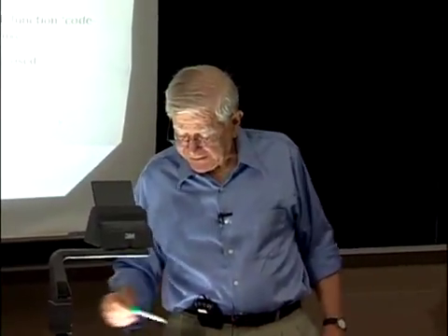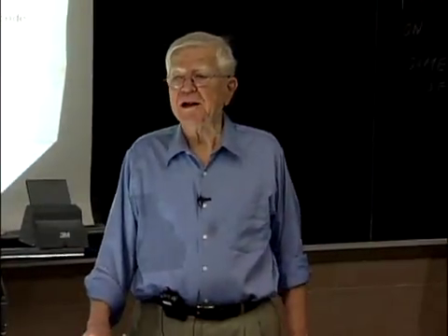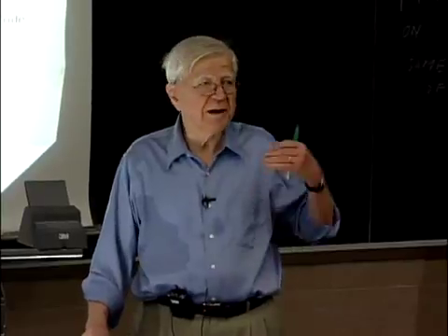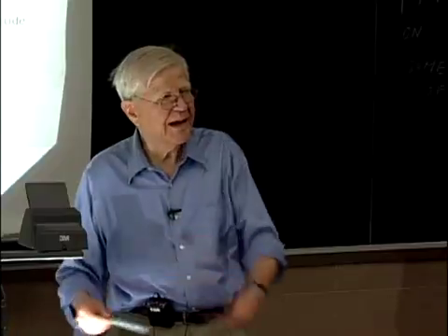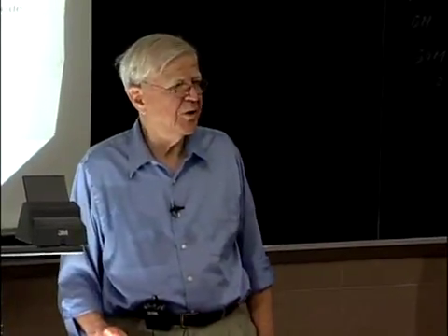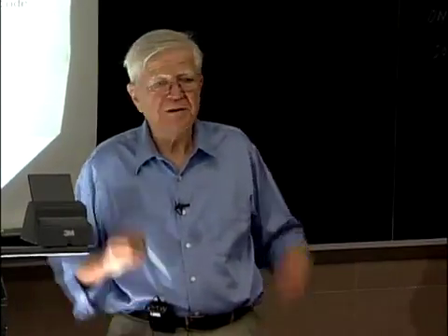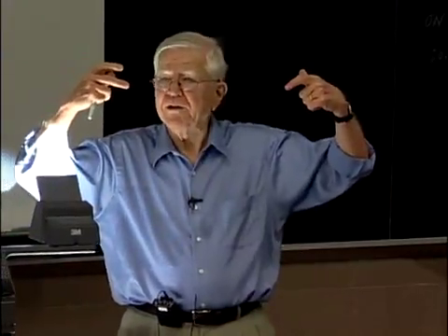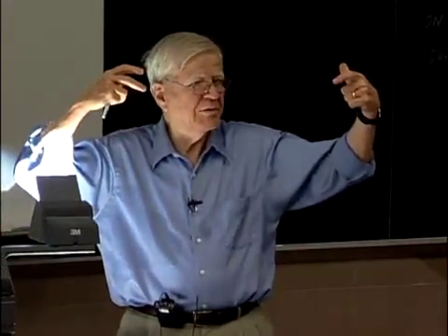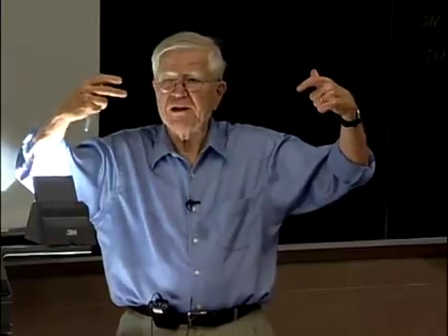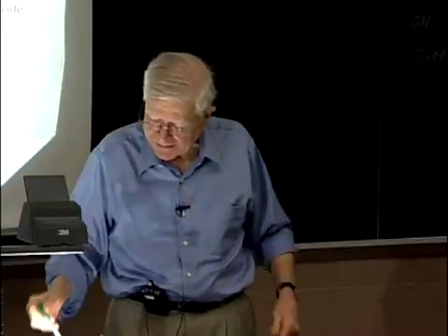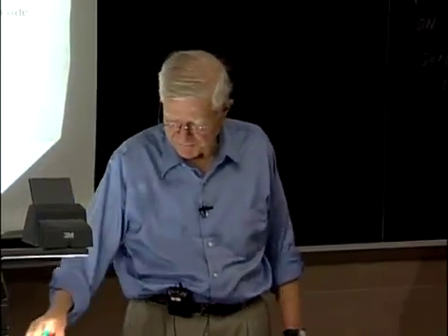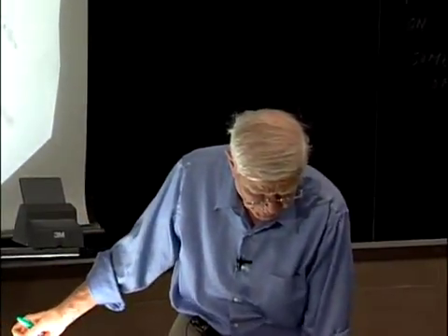So anyway, it also uses incoherent soft decisions as a way of doing its detection. We talked about incoherent detection. This rake receiver uses that instead of the coherent detection that we talked about in class. And if you just put together in your mind the lecture we spent talking about rake receivers and the one we spent talking about incoherent detection, and you put them together, you have what this receiver is doing. And we'll talk about it just a little more as we go.